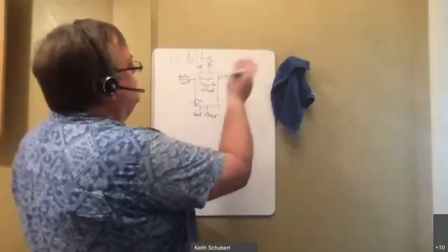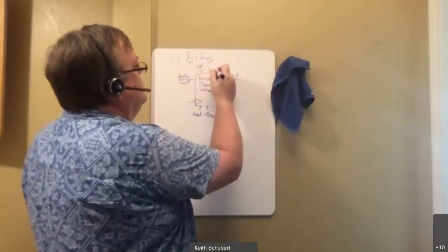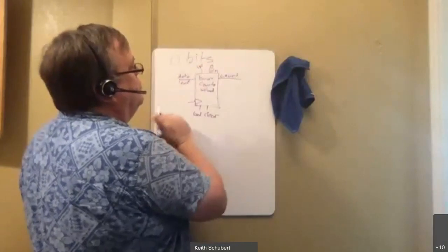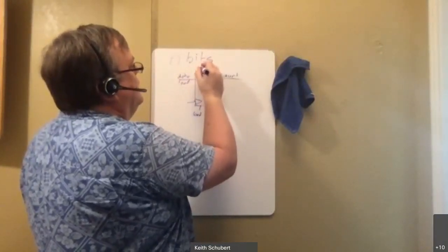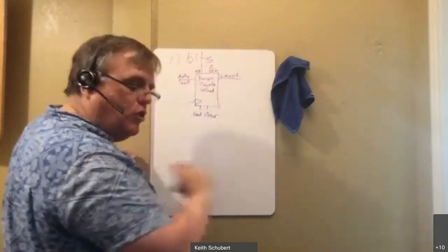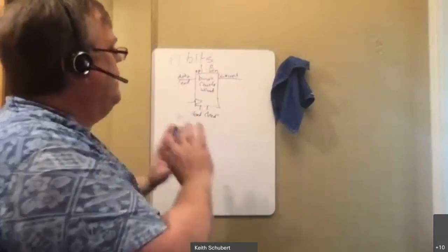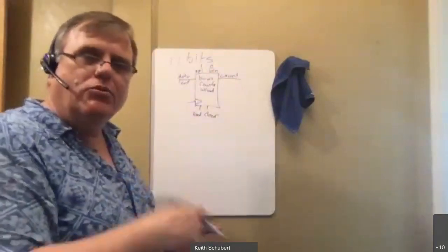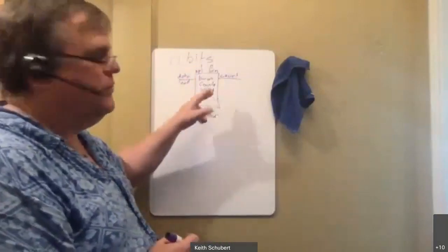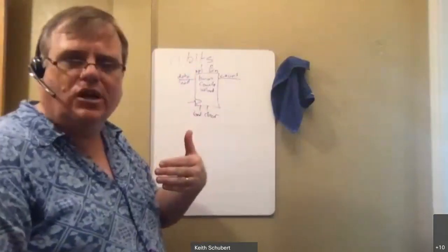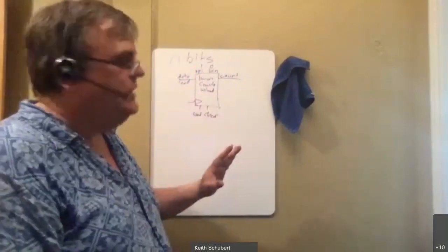well, a few ways I could go about doing it. The down count, I would set to 0. Don't count down. The up count, I'm going to set to 1. Just count up. So inside here, I just have a built binary counter that's able to do that counting based on these signals. We can talk about how we can build this, but that's essentially what we built last time. A straightforward binary counter. It's got all the states.